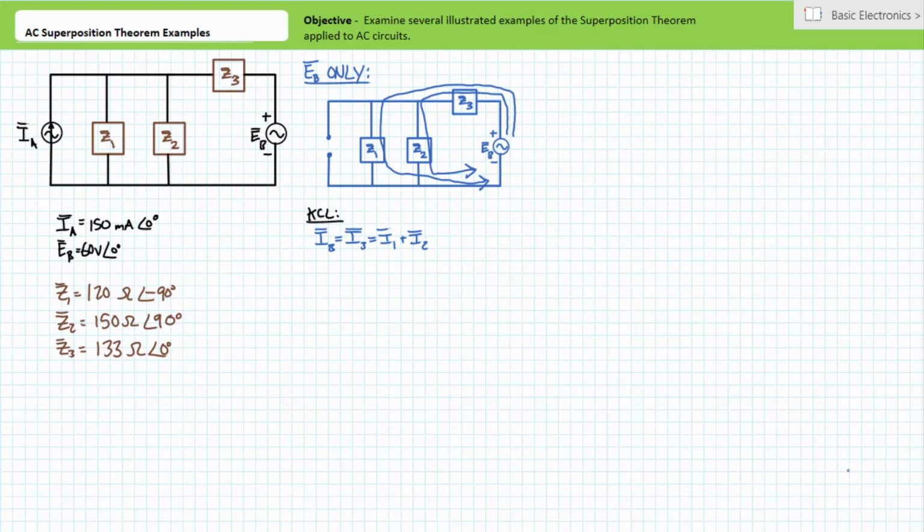It then splits into two paths. One path leading through impedance element Z1 and the other path leading through impedance element Z2. It can be said source current equals I3, which equals I1 plus I2. Given the assumed direction of current travel, voltage polarity is as indicated.